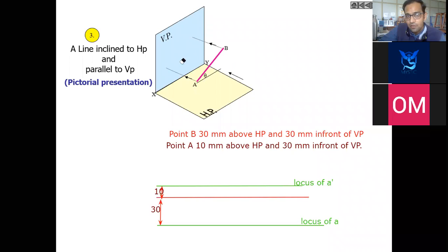The AB is going to be plotted like this, and the true length of line AB is going to be visible in the front view or elevation, and it is designating the same angle which had been available for line AB when it is constructed. तो ये जो लेंथ है वो ट्रू लेंथ होने वाला है. Front view is representing the true length of the line. But had we mentioned the length of the line in the problem? No. Why had we not mentioned it? Because the data is not available for the length of the line.